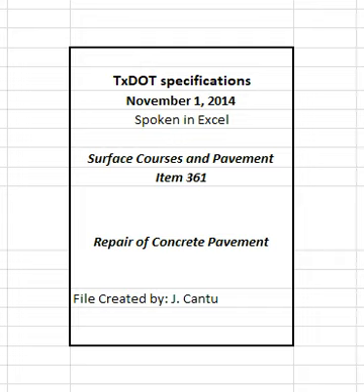Lap all longitudinal reinforcing steel at least 25 inches. Provide and place approved supports to firmly hold the new reinforcing steel in place when needed. Place dowel bars as shown on the plans for concrete pavement contraction design, CPCD, repairs. Provide and place approved supports to firmly hold the dowel bars in place.